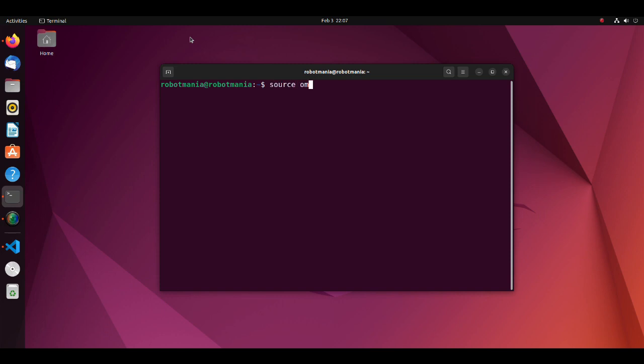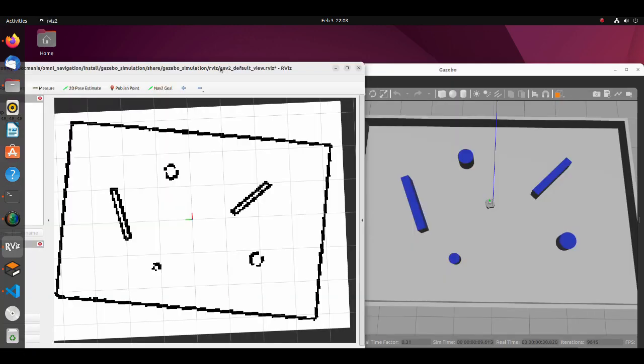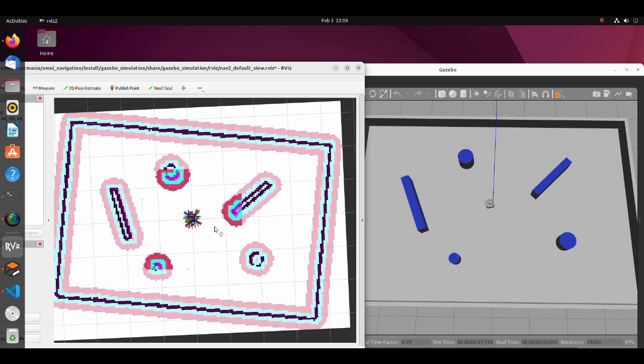To start the simulation, execute the Gazebo Sim Launch RF20 script. In the beginning we should give the robot initial position. Use the 2D pose estimate button to do this. If the robot localizes itself successfully, global cost map and local cost map will appear. After this, using the Nav2 goal function, you can set the goal position for the robot.